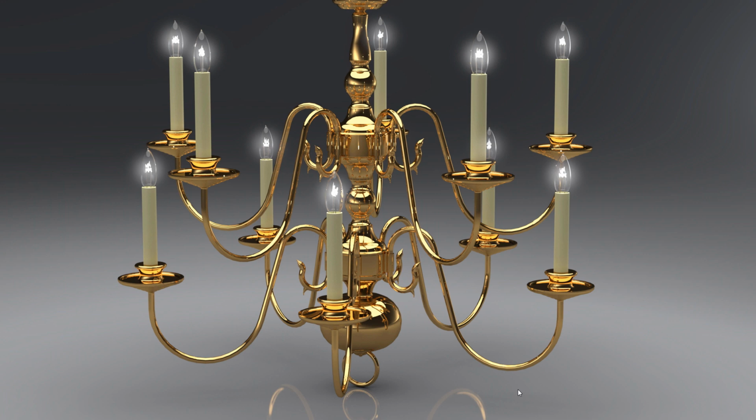And basically what I've done, if you look at the lights up at the top of these chandeliers, when I modeled that in SOLIDWORKS, I created the bulb, and that's a shell, so it's hollow. And out of the top of the candle is 2 electrodes, and then I did a helical coil with a little sweep on there to represent the tungsten element. And I made that to be a white, just a white color, okay?